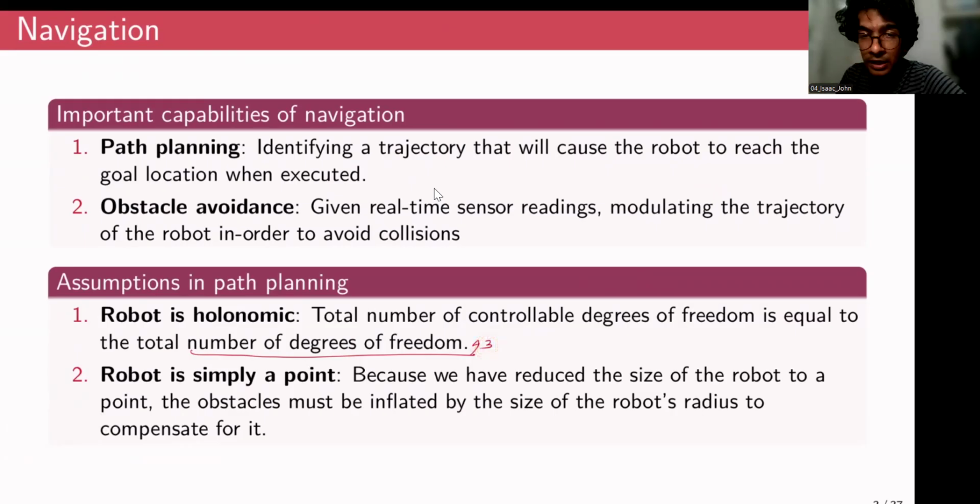And we have actually seen several systems that are holonomic, right? The one that uses 4 Mecanum wheels is a holonomic robot, right? Because these holonomic robots can move in all 3 degrees of freedom. It can move forward, it can move backward, it can rotate about its own axis with zero turning radius. It can move in the lateral direction, upward and downward. It can even move diagonally like this, right? So these holonomic robots are highly maneuverable.